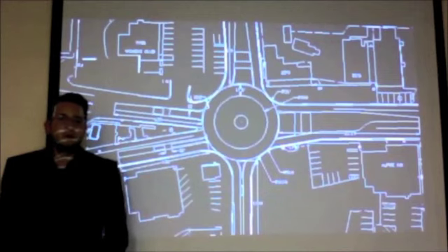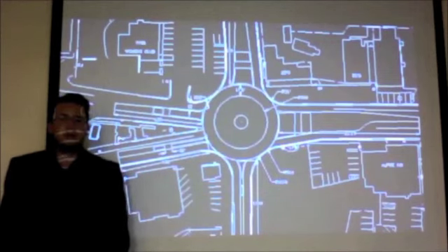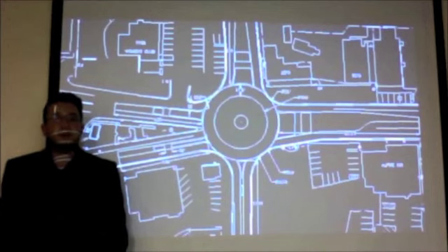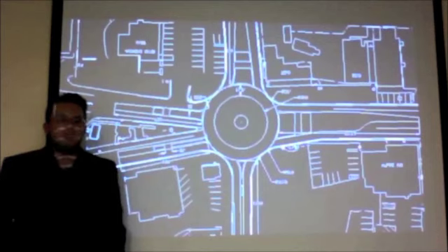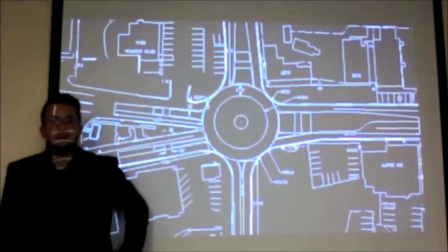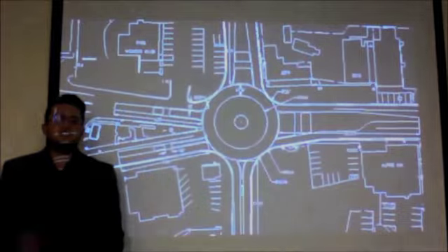Due to this, on the 5-point intersection of Alpine Boulevard, we decided to implement a 115-foot diameter roundabout where cars can travel at 14 miles per hour. With the roundabout in place, we were able to eliminate car accidents. In addition, on the pedestrian crossings, we recommended that timed crossing lights be installed to improve the safety of pedestrians.